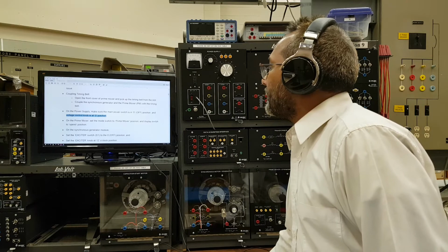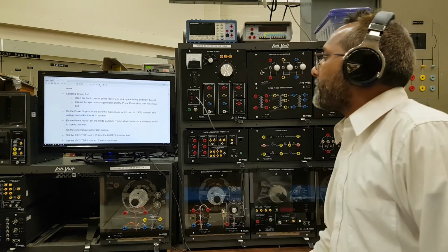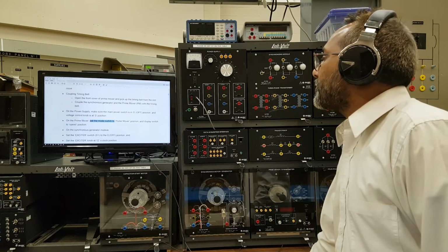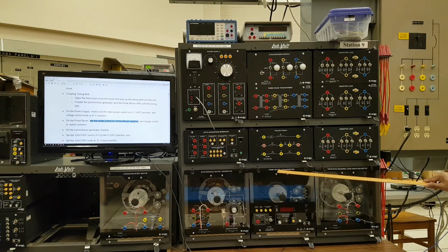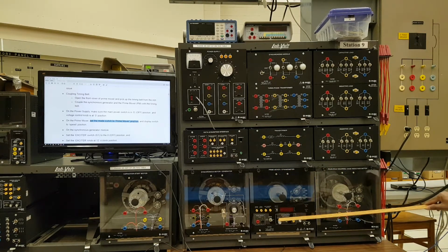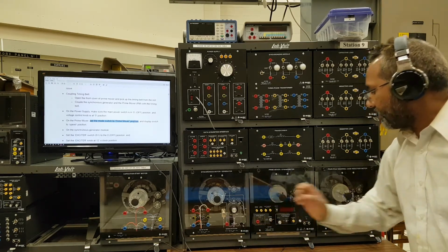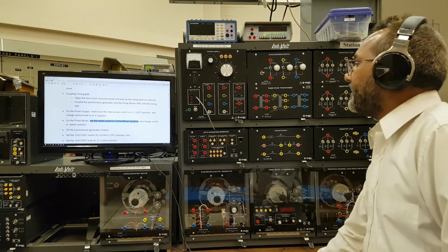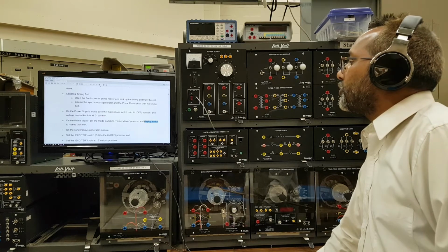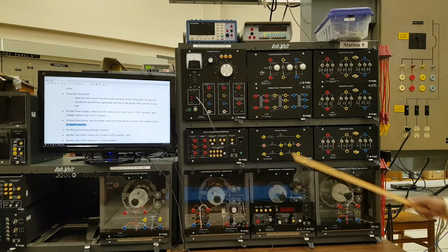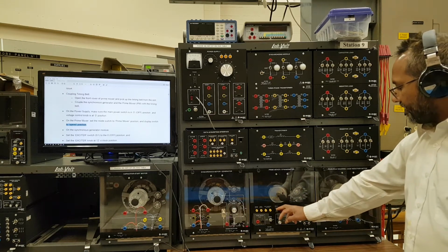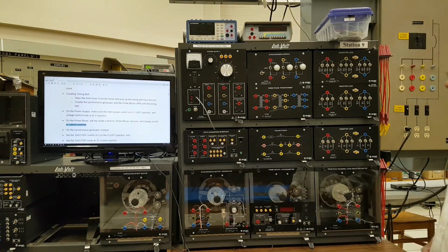And then on the prime mover, set the mode switch to prime mover position. This one you can use as a prime mover or dynamometer. So the mode switch is here, and that has to be set to prime mover because we are using this as a prime mover. And the display switch to speed position here. I think we are not bothered about the torque, how much it is giving, but we are just concerned about the speed. So we'll see only the speed, so that's why we select the speed position here.